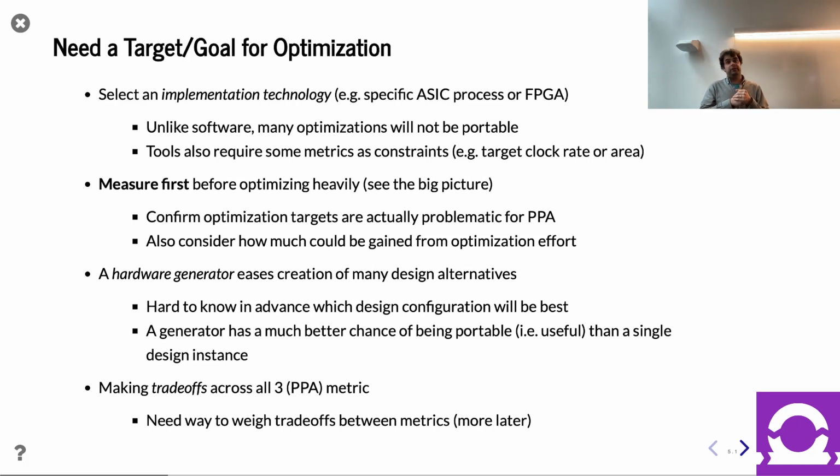Oh, great question. So comparing the logic simplification from what I write as Chisel to get spit out as Verilog, and then given a CAD tool, Verilog to the actual hardware, how does that logic synthesis optimization look? So Chisel has some logic optimization built in. It does pretty cursory stuff that is hopefully almost guaranteed to be beneficial.